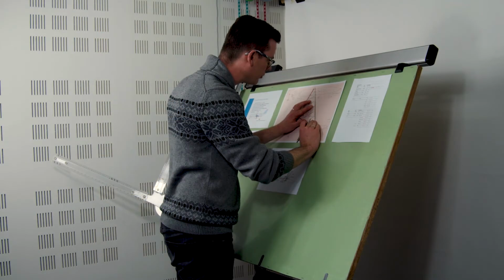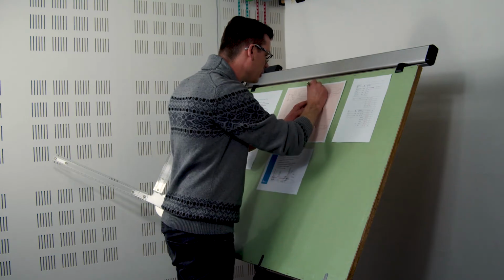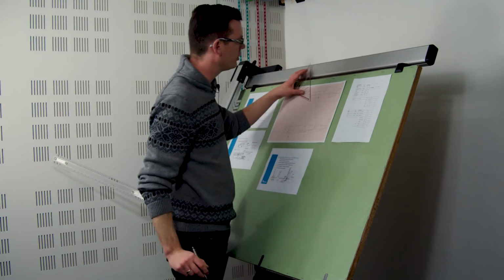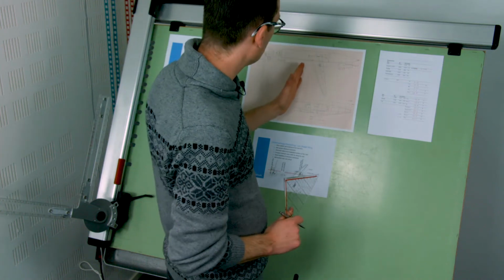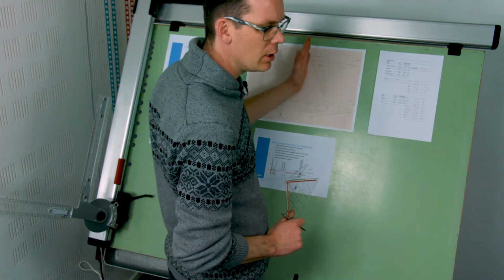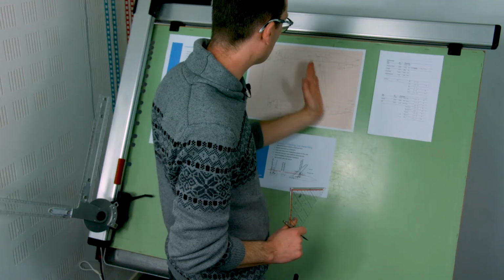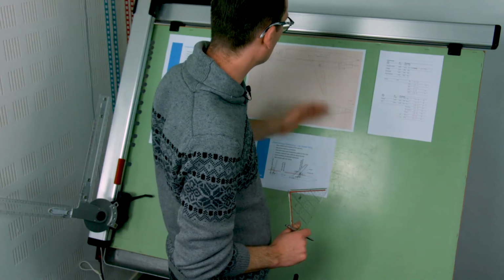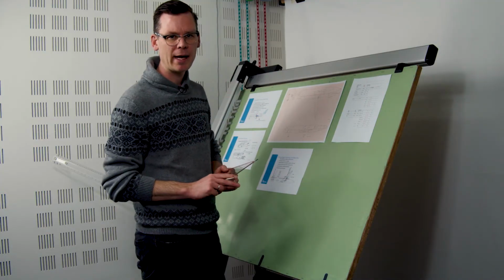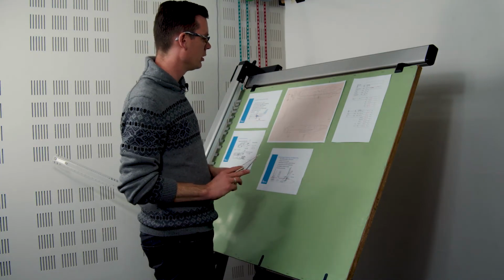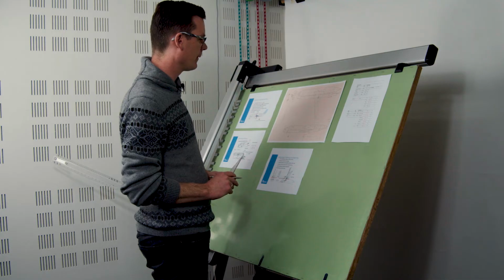Now I'm drawing in those spars all the way to the center airfoil. We know in practice that in the center wing box, the spars are not swept anymore. They're actually going across perpendicular to the longitudinal axis of the fuselage. But notionally, this is quite okay.